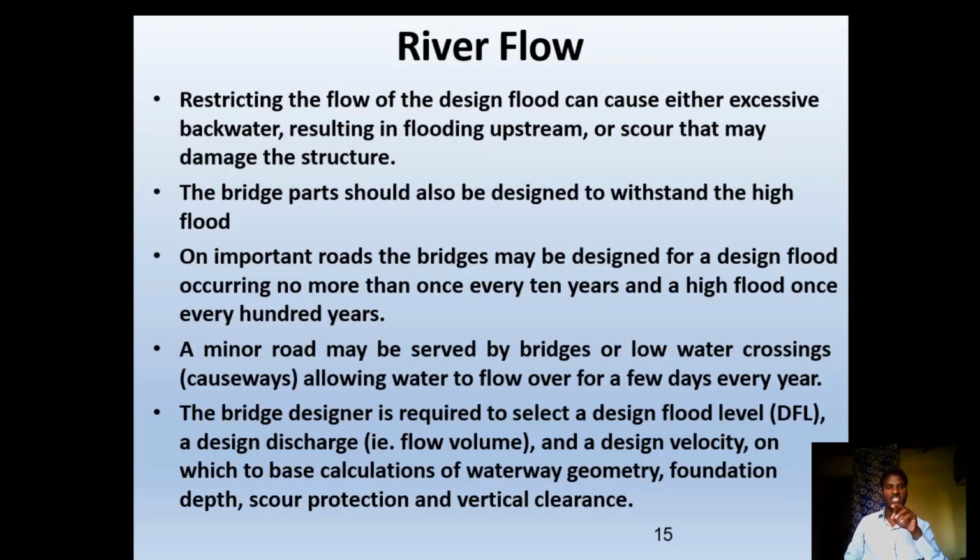Once you construct the bridge for important roads, you have to keep in mind these things: the road should flood no more than once every 10 years, and high flood once every 100 years. A minor road may be served by bridges or low water crossing, allowing water to flow over for a few days every year.